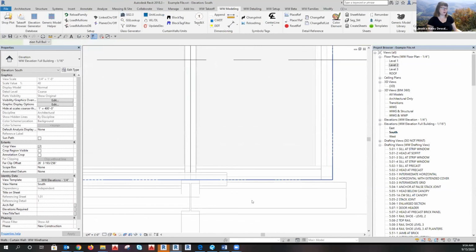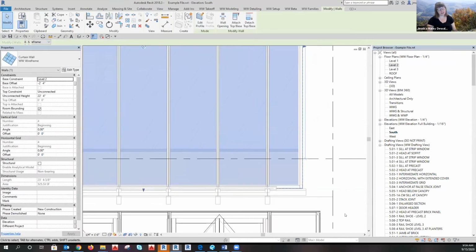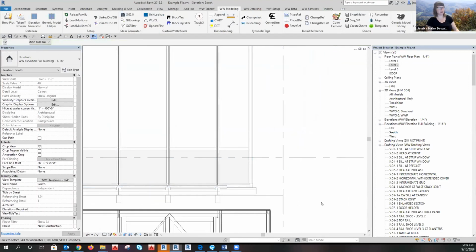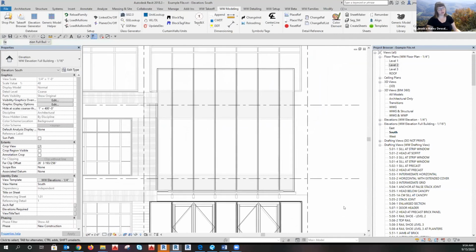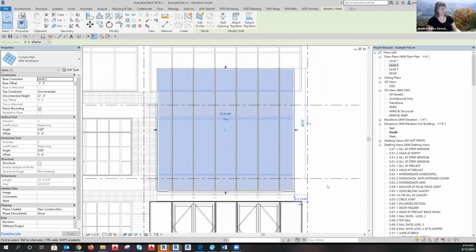And if you do it that way, you're really relying on the architect having their model in the right spot. The other option is to look into your details, do some investigative work, and figure out really where your DP is supposed to start relative to a floor line.